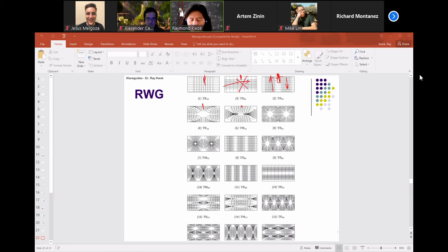So you just go through it and say, okay, these are the modes that I can do. If I do a top and bottom here, then I know not this one. You just go through, do the calculation and see the type of modes that I can pick up for TE, and then you have to look at TM also, and then say which are the first 5 modes that I would pick up, the lowest 5 frequencies.